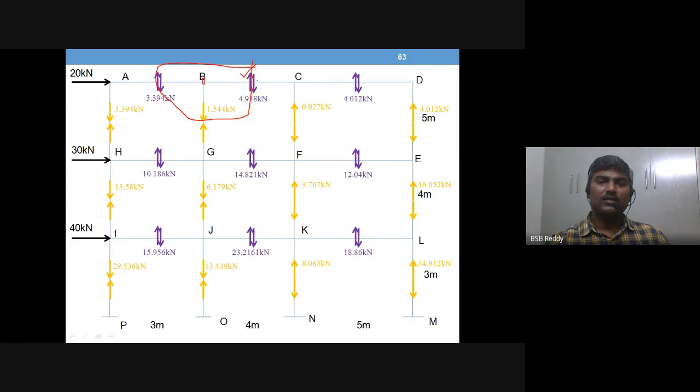So now the other arrow you draw just automatically, from equilibrium the other arrow is downward. Okay, so this is how we complete the top shear. Okay, so it is like you take a free body diagram separated by the point of contraflexures associated with a joint. Okay, always go for a free body diagram associated with a joint. Right, going for the next.